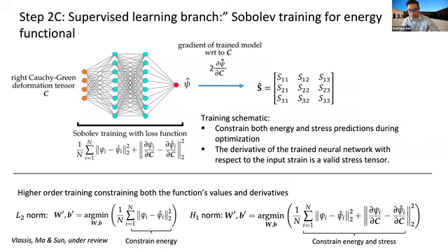And we seem to have found a promising lead. When we want to generate a constitutive law, instead of outputting the stress, I would output only the energy. However, I would also use the first derivative of the energy, in this case the stress measure, as an additional input for the loss function to help me adjust the weights. And I can also use the second derivative, which is the stiffness components, to help me regularize the data.